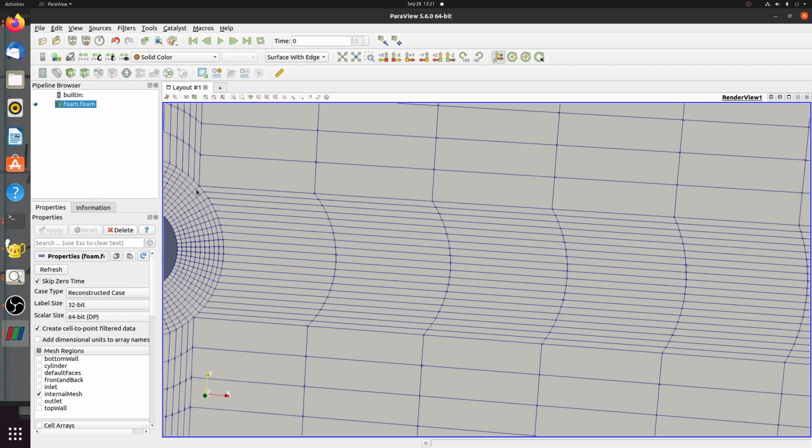I think he thought it was my finished mesh. He wanted to remind me that the coarse mesh should not be 20% or greater than the refined mesh, so 20% greater than the fine mesh when you go from fine mesh to coarse mesh.